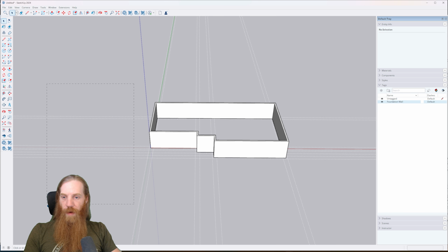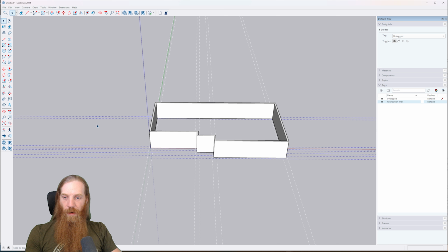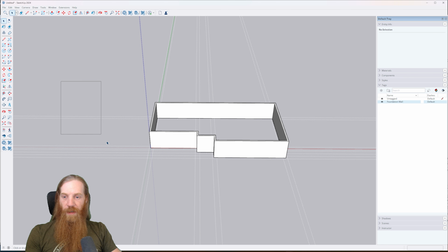You can also just hit escape to deselect it. Now if you click and drag the mouse, if you drag it to the left, it'll select anything that has even just part of it inside that selection area. Because all of these reference lines were in, part of them was inside that selection area, it selected them. If you drag to the right, notice it does not do that.